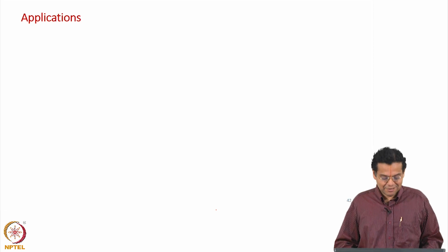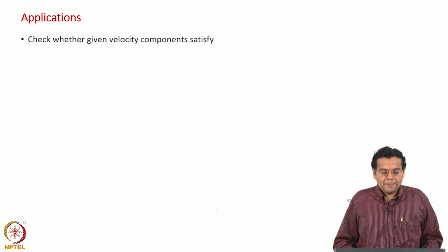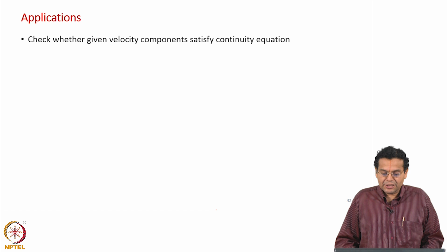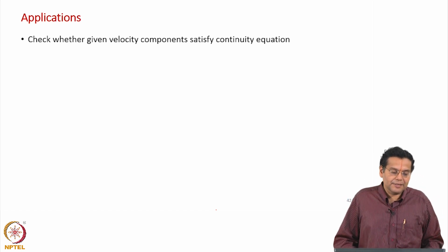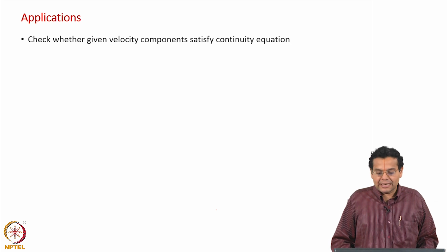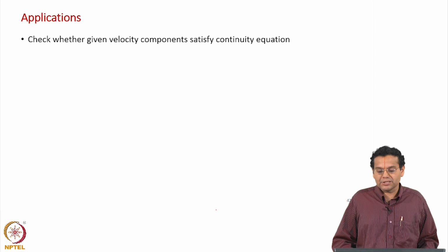So, let us look at applications of the differential total mass balance equation, or the continuity equation. The first application is that suppose you have arrived at some velocity field, meaning you have found expressions for Vx, Vy, Vz. You can check whether the given or found velocity components satisfy the continuity equation.